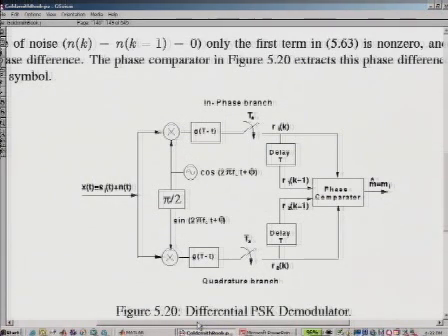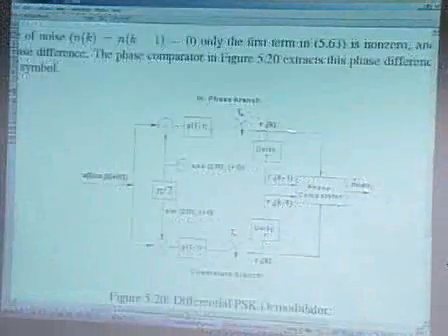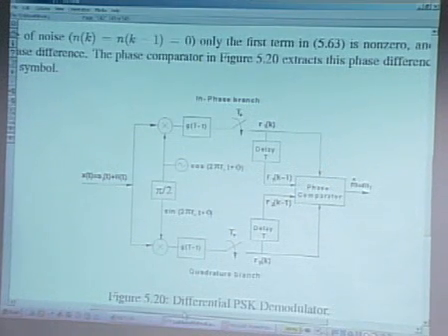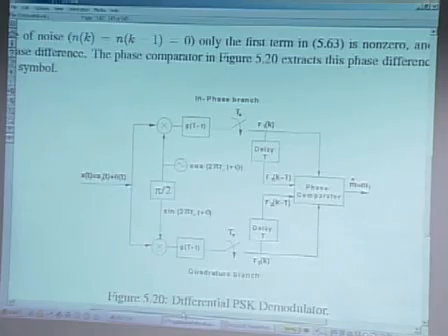All right. So we're going to compare the phases of one symbol with the previous one, so this is a storage memory unit that stores the symbol. So you can compare it with the symbol that comes right after. Okay. So a symbol is stored here in memory, and then the next one comes here, and these two are compared. So we can see the phase change between consecutive symbols and make a decision on that. Okay.